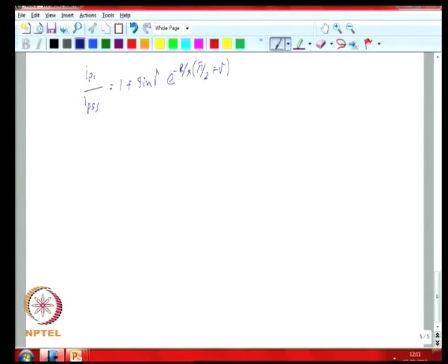So, for the numbers in the given problem, this value is about 1.37 as your peak to steady state fault current value. Okay. So, if you then look at what could be the second peak, you can get an expression for the approximate location of the second peak.